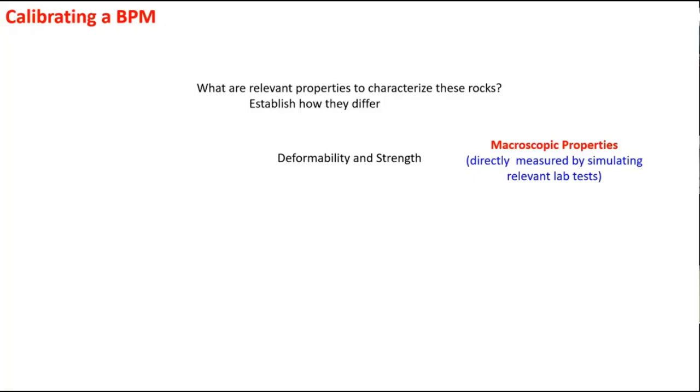Do you remember that shell thing I showed, that circular plate with pressure? Well, that thing keeps getting more and more pressured, and eventually you reach a certain pressure. It doesn't break. It just, the pressure displacement curve just goes flat. So that's a certain type of failure. So you could say that was the critical value of pressure. So we're going to call that the strength, right?